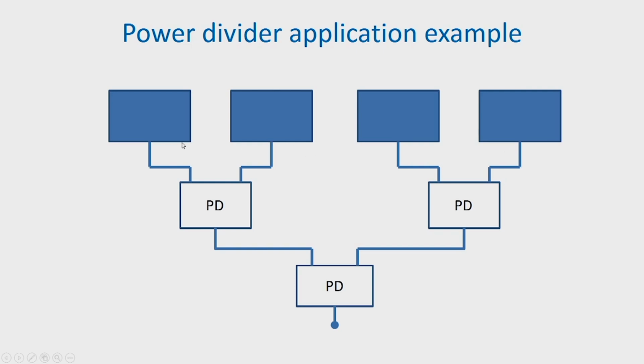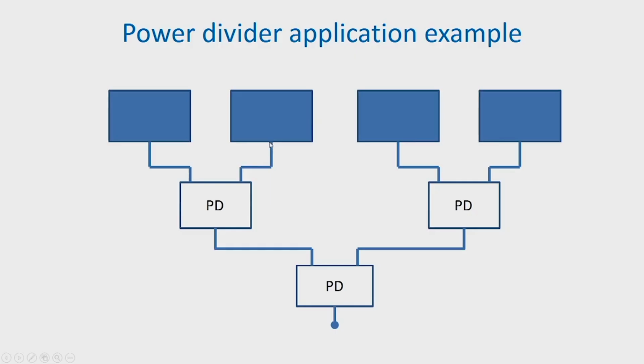If we want the elements to be excited not uniformly, having different excitation levels at individual antenna elements, and also the phase to change, this type of power divider circuits with unequal power division can be made, and we can use additional phase shift.